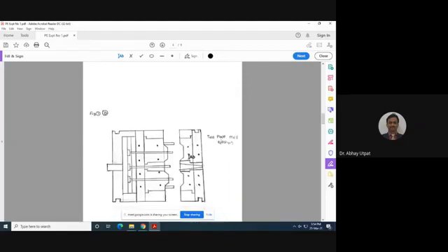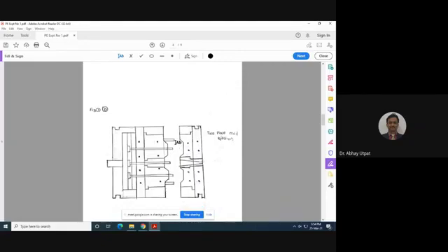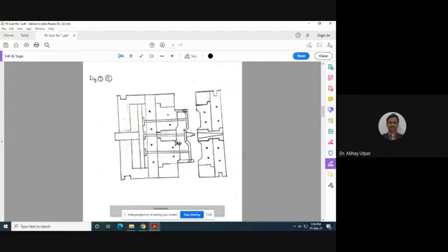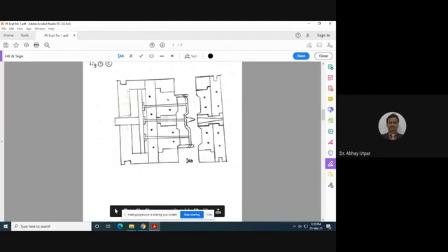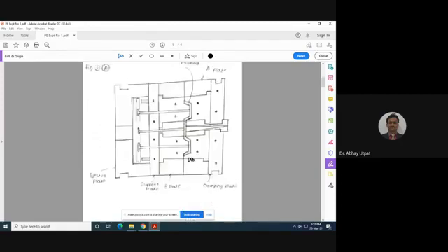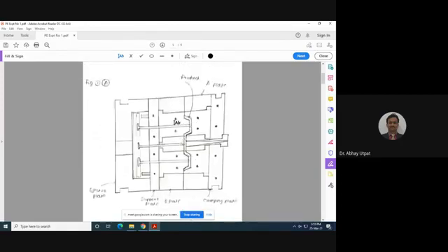And later on, where is the product now? The product falls in the bin, and now the mold is ready for the next cycle. So I repeat once again. Now I will go the reverse way, next cycle. So this will be closed. There will be a small gap. Then there will be injection through this point. Once there is injection, you will again come back to this step.